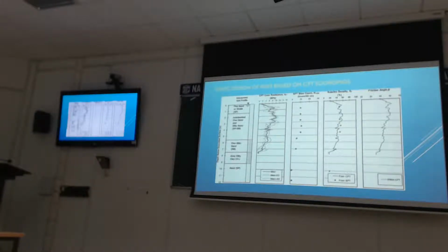What that tells you is the drain parameters are probably quite good. It's just that your cone is being pushed too quickly, you've got pore pressure around it, and you're losing your QC. Okay. So there is a bit of interpretation to be done with the cone test as well. It's not a blind game.